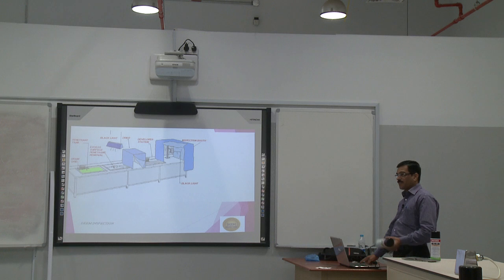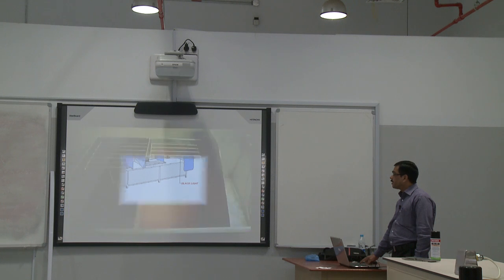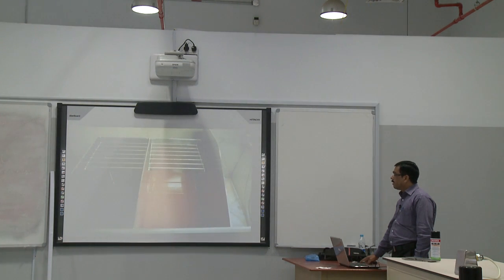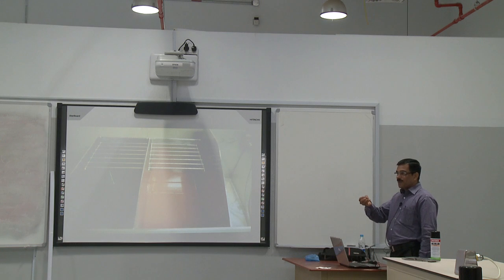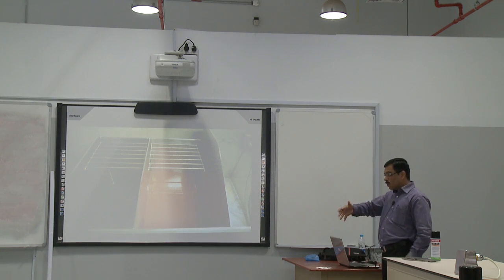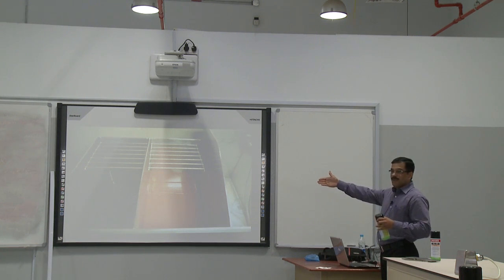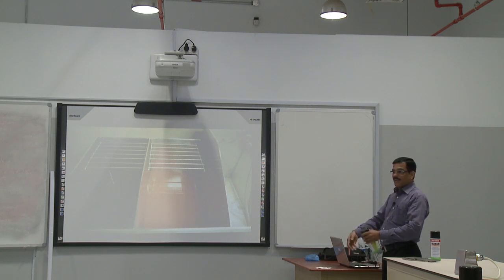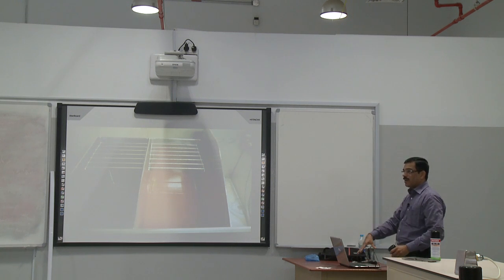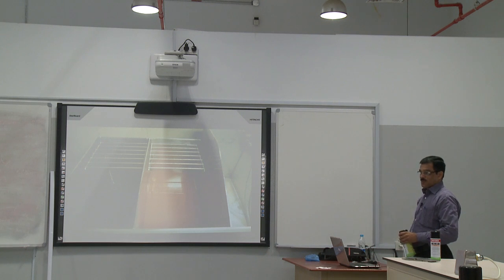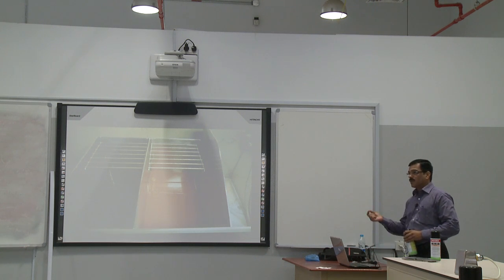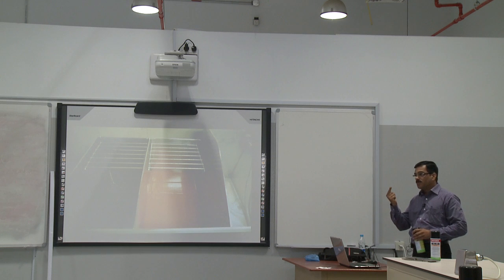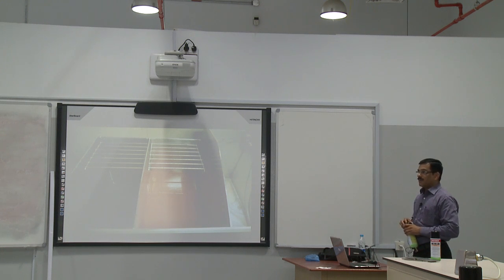Big manufacturers use different types of development systems, like tanks. If they are handling small materials, with too many minor pieces, they prepare the penetrant in a big tank, put all the material into the tank, and process it. Tanks are used for defense materials or minor parts like small nuts and bolts.